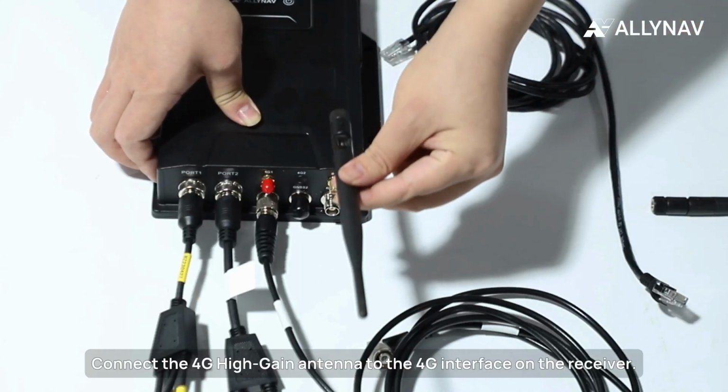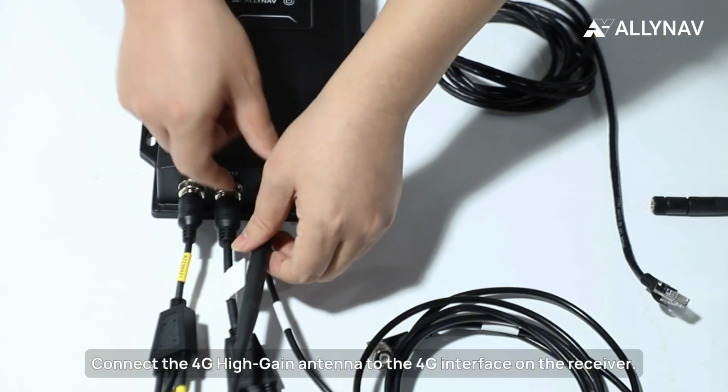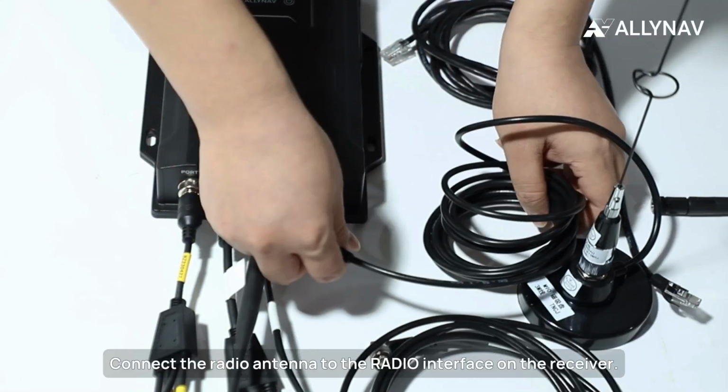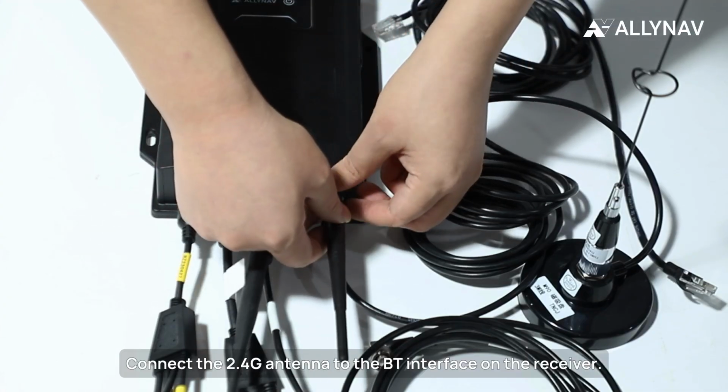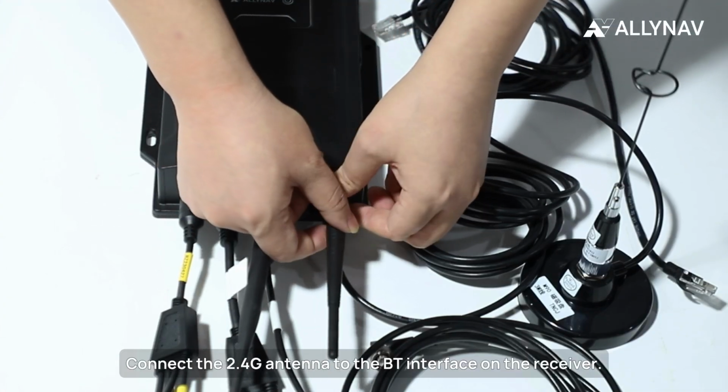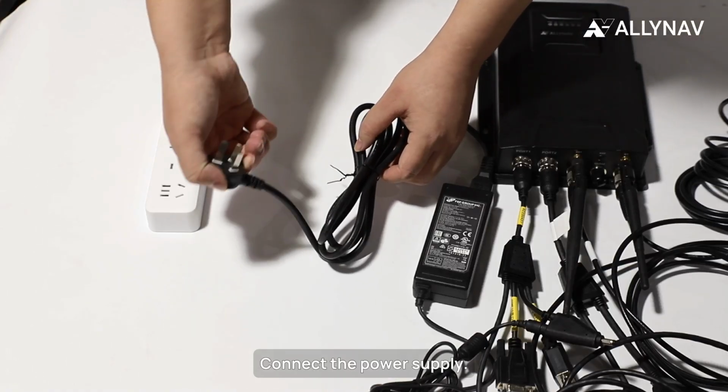Connect the 4G high-gain antenna to the 4G interface on the receiver. Connect the radio antenna to the radio interface on the receiver. Connect the 2.4G antenna to the BT interface on the receiver. Connect the power supply.